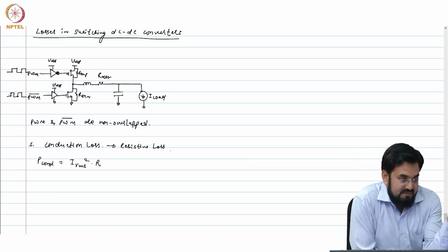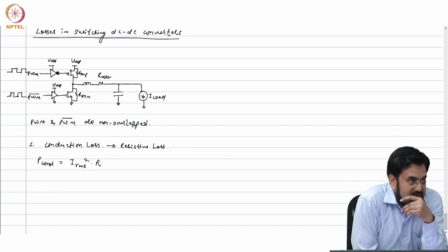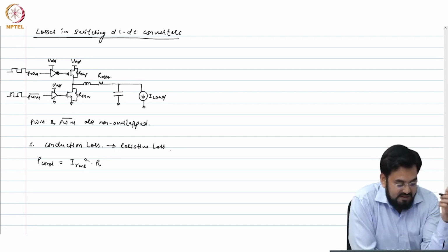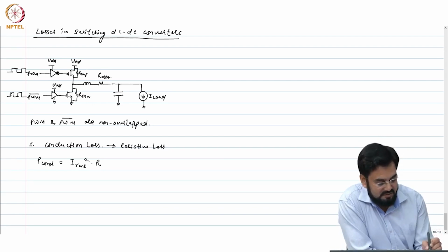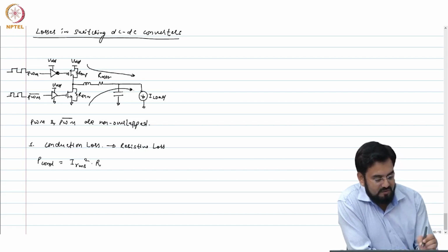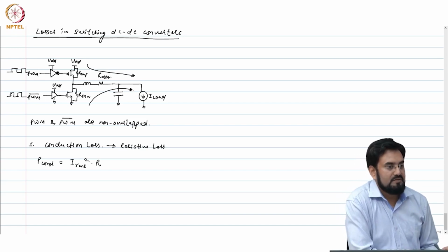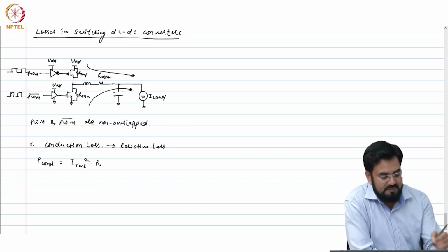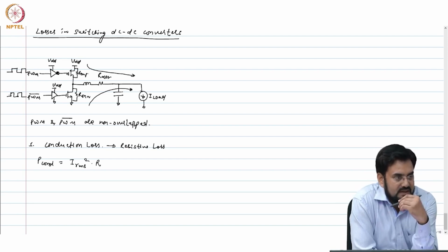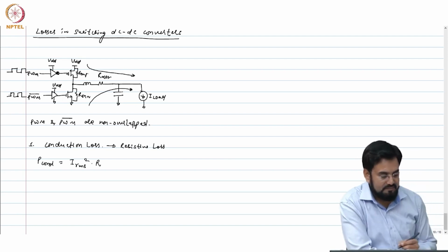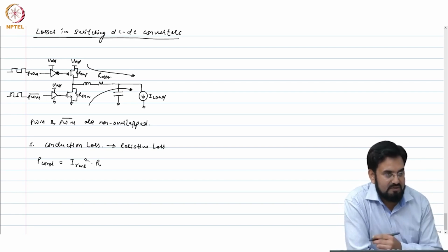And resistive losses are defined by I square R. So whatever the RMS current is in the conduction path, so this is your current path. When PMOS is conducting, it's going through R on P and RDCR and goes into the load. Okay, and we already talked about this.